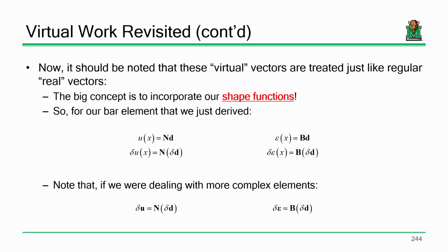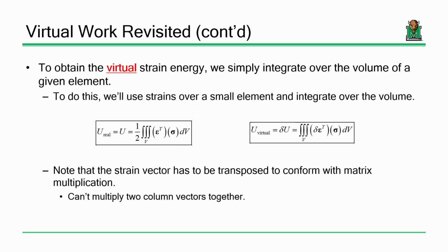Okay. Now, keeping that in mind, this whole concept of energy, keep that in the back of your head. I might write it up here on the board, although I'm going to use the whiteboard on the screen in a second. So I'll say my virtual energy, because that's the only one I'm really going to care about, is the integral over the volume of delta epsilon transpose times sigma, integrated. I'm going to use the board in a second, so I want you to see where this is coming from. Everybody all right?